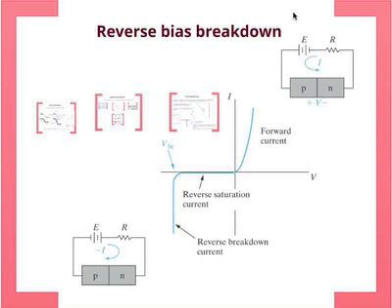Because they're important for our practical applications, as we will talk about today in the class as well. The first is the Zener breakdown. There are two mechanisms for breakdown. First is the Zener breakdown, which happens at lower voltages. This has to do with electron or hole tunneling, a quantum mechanical effect. The second is for high voltage applications, which is the avalanche effect, very much like an avalanche on the ski slopes and so on. We'll talk about that today.